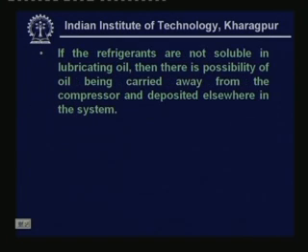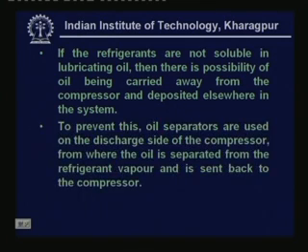Okay, if the refrigerants are not soluble in lubricating oil, then there is a possibility of oil being carried away from the compressor and deposited elsewhere in the system. This is another important problem. If the refrigerant is not soluble, then oil will be carried out of the compressor, okay. So in such cases, we have to use what is known as the oil separator on the discharge side of the compressor, from where the oil is separated and sent back to the compressor.